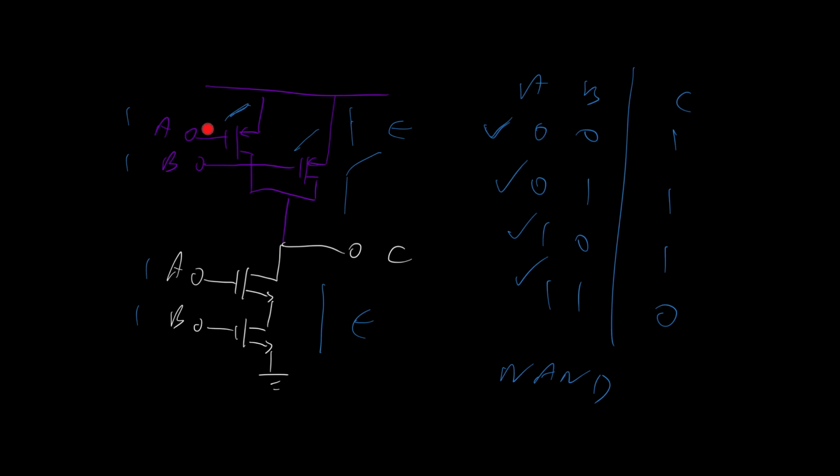Well, remember that these switches here correspond to the ideal case. In actual fact, as A changes from 0 volts to 5 volts, we're going to get a variable resistor here, and its value might range from, say, in our SPICE simulations that we did, about 1k to, well, we didn't actually show it, but let's say 1 mega ohm or something.